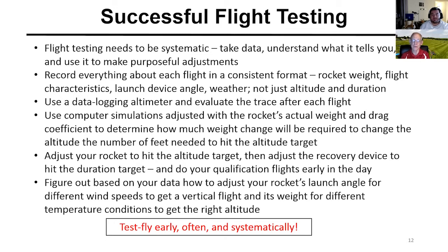It's good to use a data logging altimeter, the Peanut, for example, to look at those traces of altitude versus time to more deeply understand what your rocket really did. We don't use those traces for score reporting. We only use the beeped out altitude. We don't have time to sit there and look at traces in the finals, but in your test flying, you should be using an altimeter.